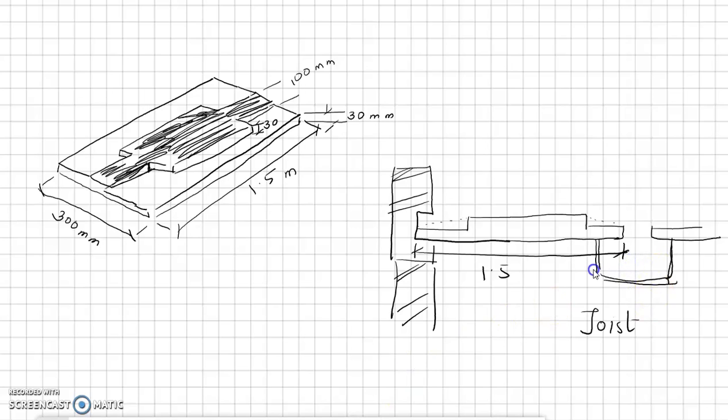So these beam joists will have steel like this. So you have steel here. It's way much above. Not able to draw properly. So then once all these panels are placed like this, here there will be concrete poured. So here there will be concrete poured. That's how then it becomes monolithic. It has to be fully nicely joined.